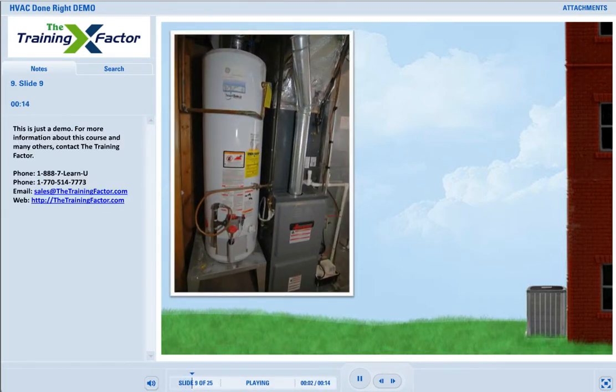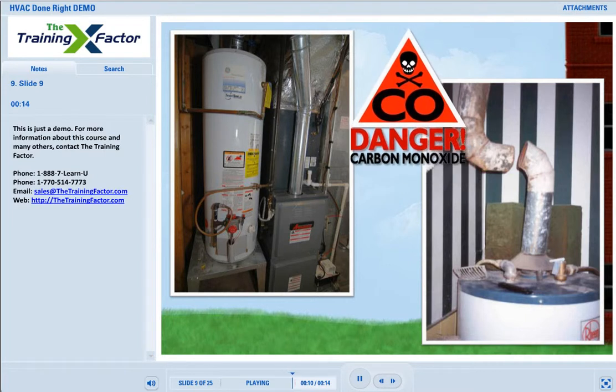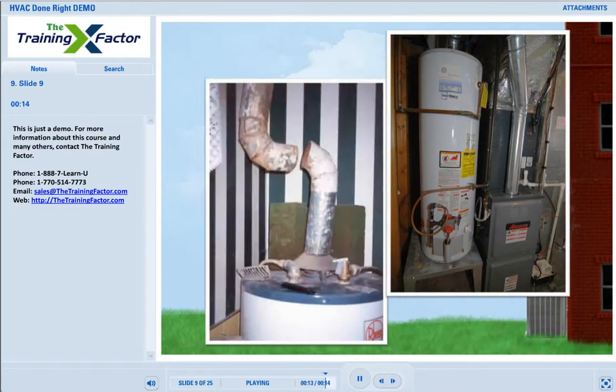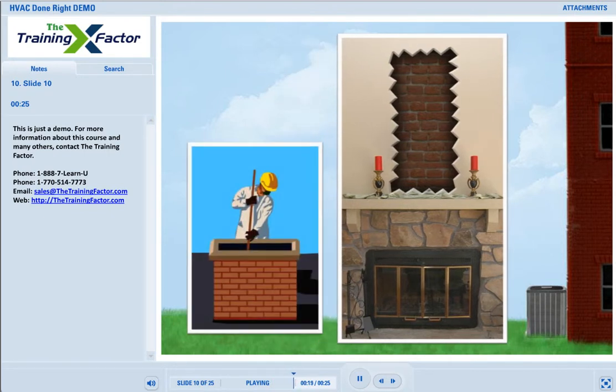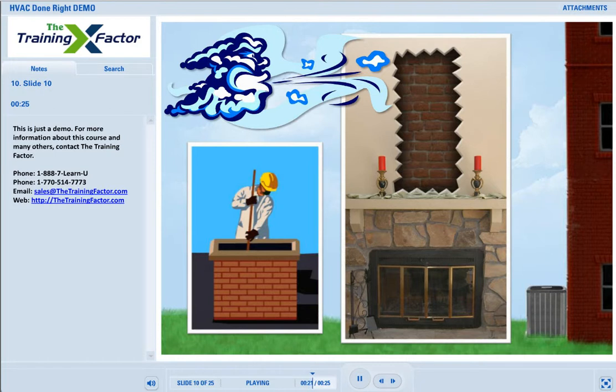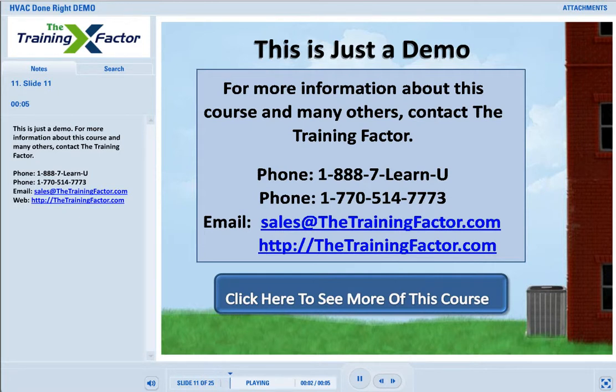Properly functioning chimney systems will carry combustion byproducts out of the building. Therefore, chimney problems put you at risk of having these byproducts, such as carbon monoxide, spill into the building. Most older gas furnaces and boilers have naturally drafting chimneys. The combustion gases exit the home through the chimney using only their buoyancy combined with the chimney's height. Naturally drafting chimneys often have problems exhausting the combustion gases because of chimney blockage, wind, or pressures inside the building that overcome the buoyancy of the gases.